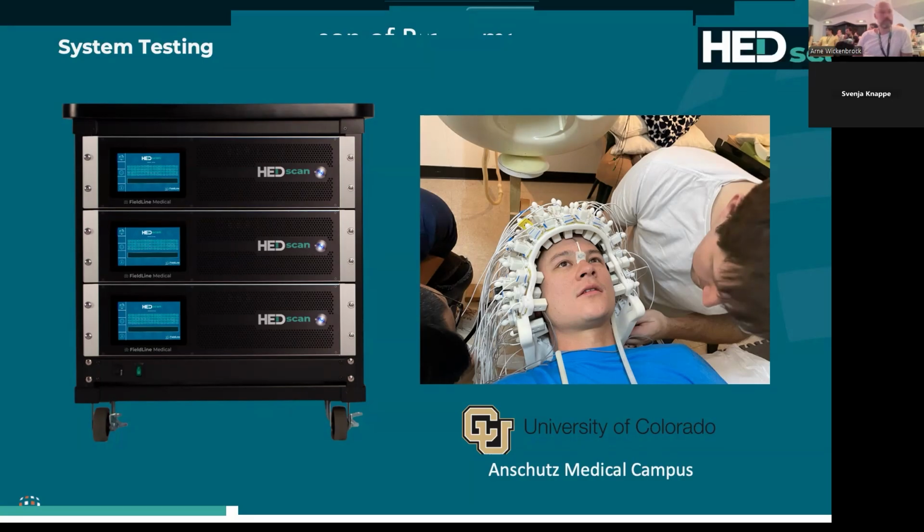Also, there's local heating on the skin. So we need to, of course, do a lot of thermal management inside these. We have to comply with a surface temperature limit set by the FDA of 43 degrees. And so we do have to do a lot of thermal management. It is something the OPM makers are learning, how to control that heat and not have it go into the subject, but rather stay in your vapor cell.